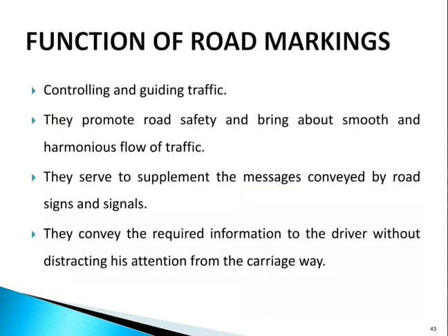Next, let us see the functions of road markings. The functions of road markings are controlling and guiding traffic. They promote road safety and bring about smooth and harmonious flow of traffic. They serve to supplement the messages conveyed by road signs and signals. They convey the required information to the driver without distracting his attention from the carriageway.